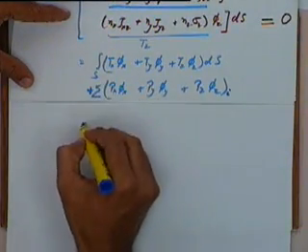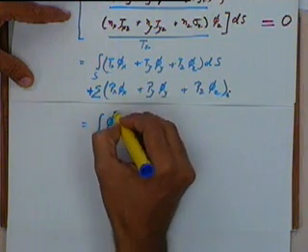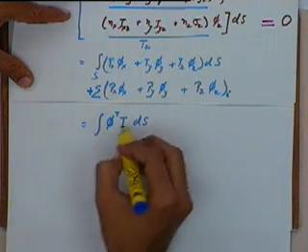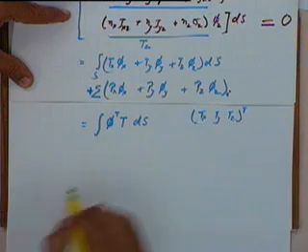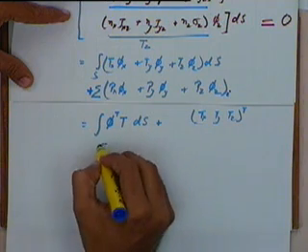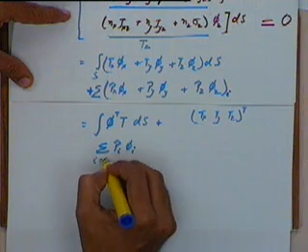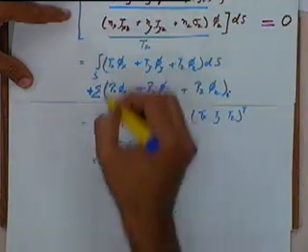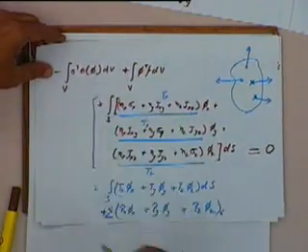these two terms will become, now this is nothing but the integral of, I can write this as phi transpose T ds, okay, because I am using T will be nothing but Tx, Ty, Tz transpose, okay, and this would be this plus sigma Ti phi i going from 1 to n if I have n point loads, okay. So this expression will give us these two terms, and this complete expression, okay, that will become